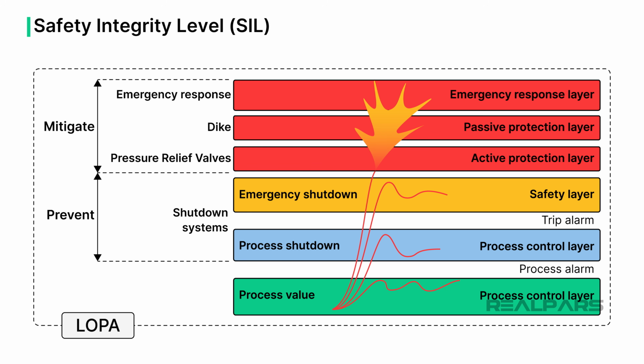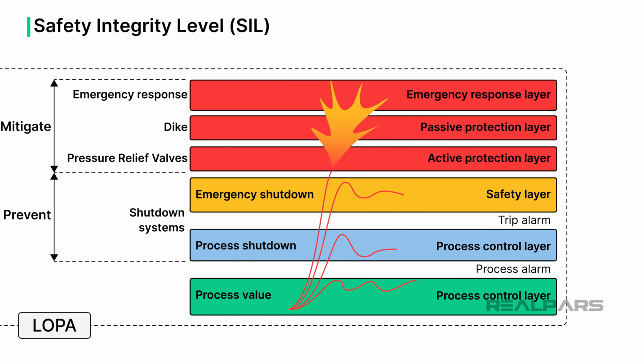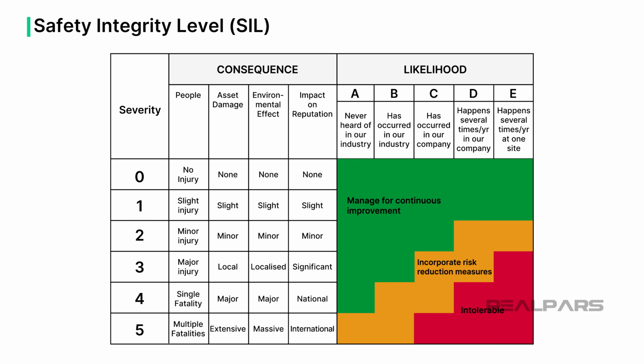There's the layer of protection analysis, or LOPA method, whereby all known process hazards and layers of protection are carefully examined. Some companies use an assignment matrix to assign a SIL based on a qualitative ranking of the event likelihood, event consequences, and the availability of regulatory process control safeguards already in place.